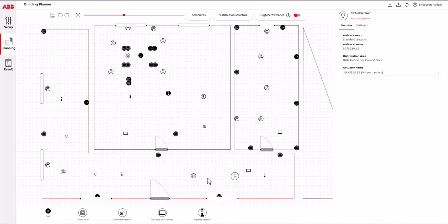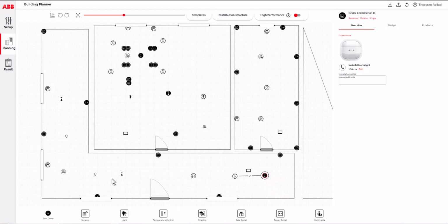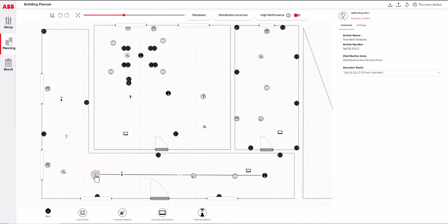If it is an element with channels, e.g. rocker of a push button, click on this channel, select the load circuit, e.g. light, and thus functionally connect them via a connecting line. Advantage: the installer, who later configures and programs the KNX devices with the ETS, receives the relevant information. You can delete it again by clicking on the magnet in the connection line.